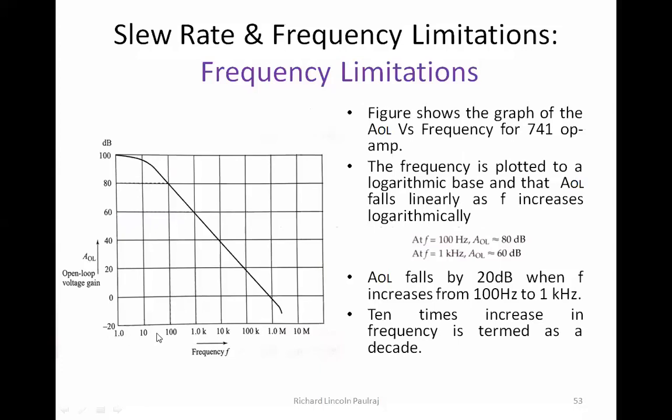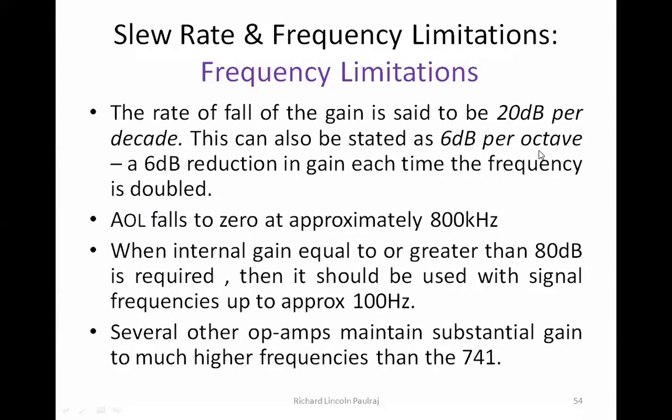If I look up for 20, the value here for 10 and 20 should have an approximate difference of about 6 dB, right? Now when I see 100 and probably 200, the levels of these gains should have a difference of about 6 dB. So that is referring to octave. I hope this is clear to all of you, right?